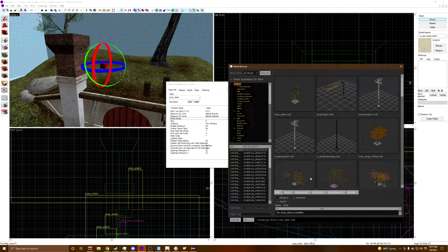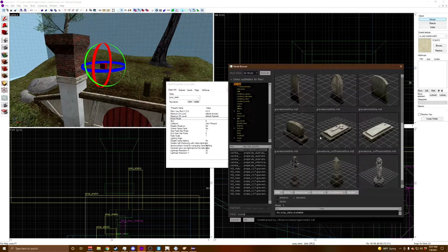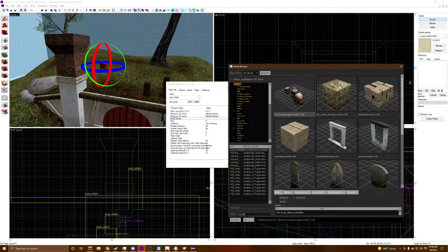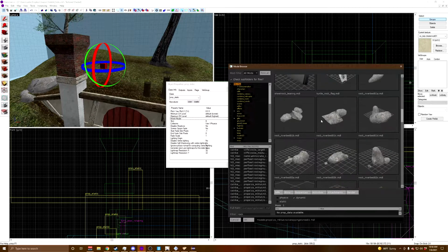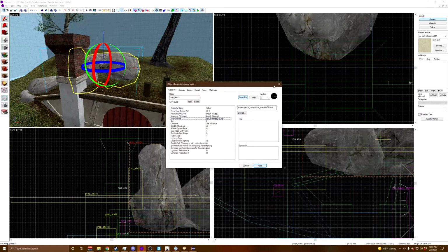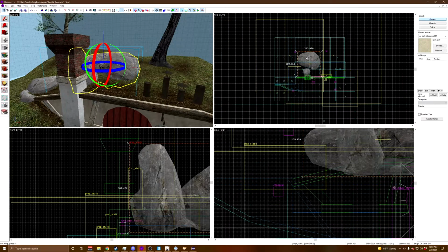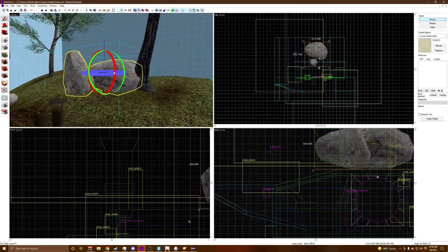2. You can place props in your level by going to your Entity tool and typing in prop_static. There are 3 primary different prop types in Source: static, physics, and dynamic. Static places a prop that doesn't move, it just sits there and looks pretty. Physics props will create props that can be moved around. Dynamic props work a lot like static props, except you can tell them to perform animations if they have any.